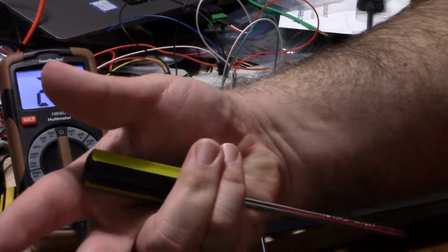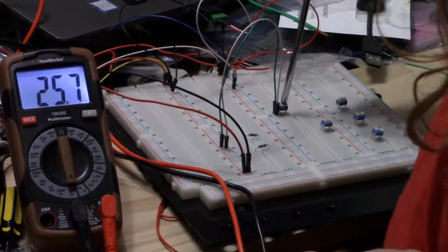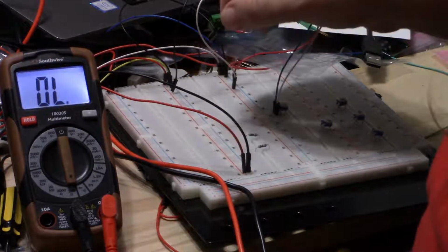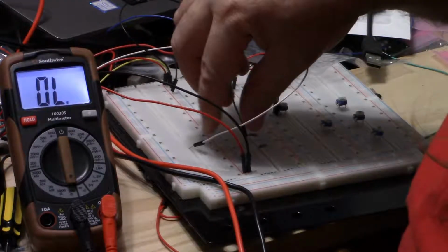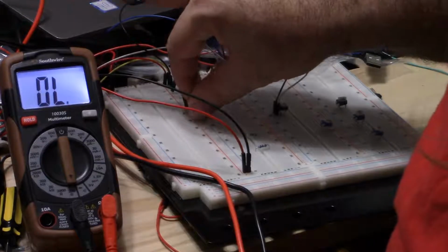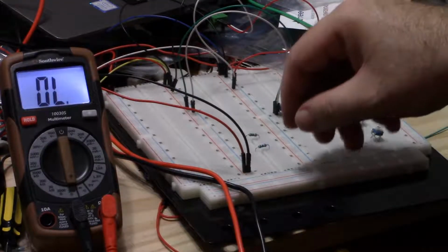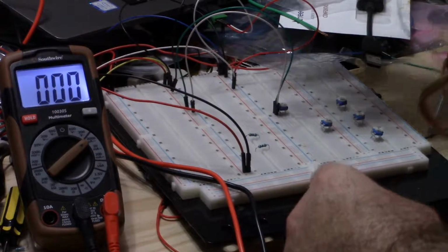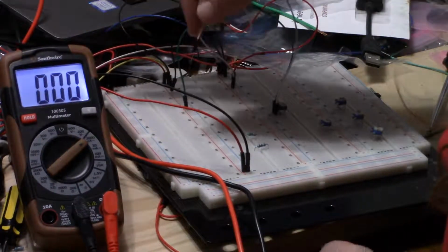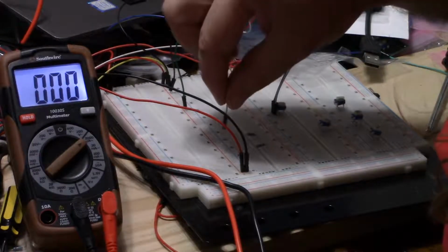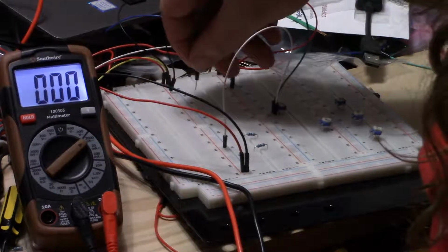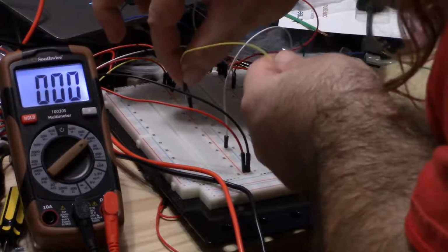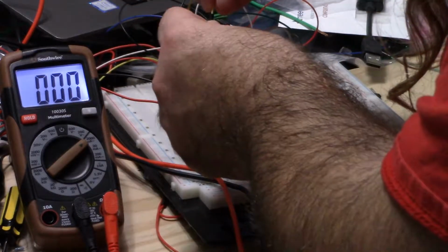We can calculate current from that. So first I'm going to turn it up. So we get a little over 100. And now I'm going to plug it not across the multimeter, but across the signal. Make sure nothing explodes or catches fire. Seems all right. So now I'm going to insert the multimeter in current mode into this circuit. So now the multimeter should have almost no resistance. So let's say that's going to be a negative connection through the resistor. And we'll do a positive connection to the positive terminal of the multimeter.